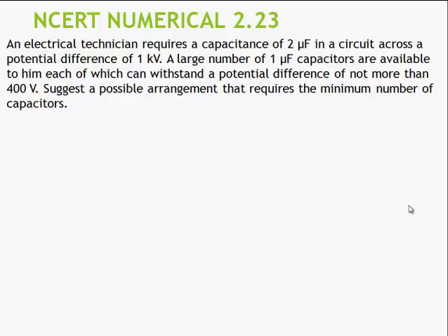So remember, if I add 2 capacitors, since the original voltage of the supply is 1000 volts, the voltage across each capacitor will come out to be 500 volts. Again, the capacitor will burst. So we require one more share. So let us apply 3 capacitors in series. So every capacitor will have 333 volts. Now it is safe enough. That is how we try to find how many capacitors are to be added in series.